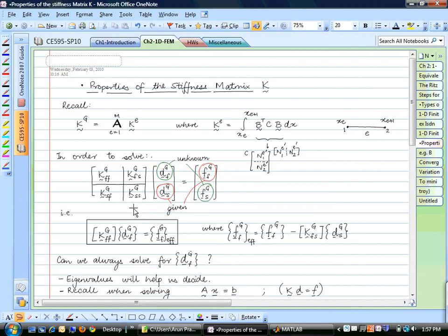And what that means physically is that you have this entire big structure, and you're applying some forces to it. It can be in equilibrium at this place, or you can take that structure, move it to a different place, give it a rigid body translation. It would still be in equilibrium. So this solution would not be unique. It can be translated by a rigid body translation. So that's why this is a positive semi-definite equation.